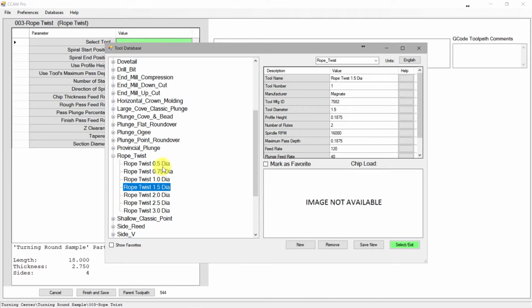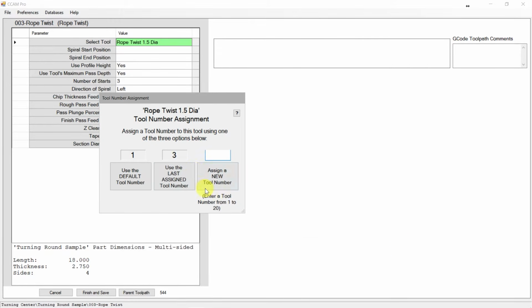It will give you slightly different results in the look of the twist based on the size of the cutter relative to the stock diameter. And so I want to see if I can give you a good way to find which one would work best based on what you are turning at that time. Okay, so if we select this tool, let's go back to our drawing board.